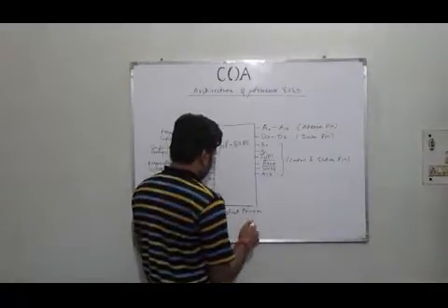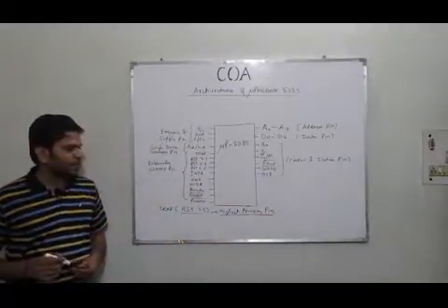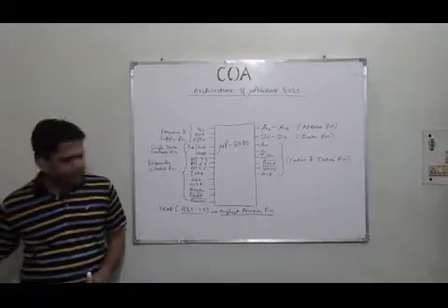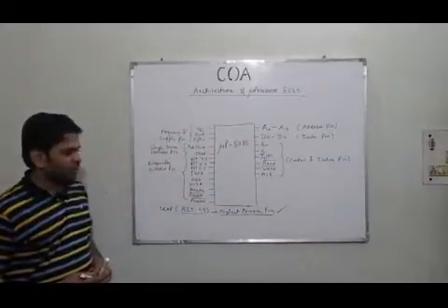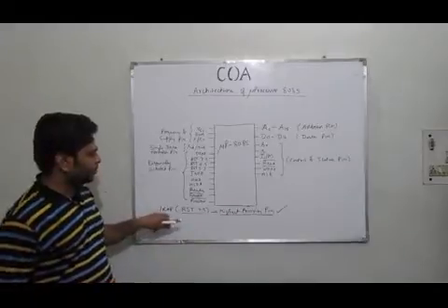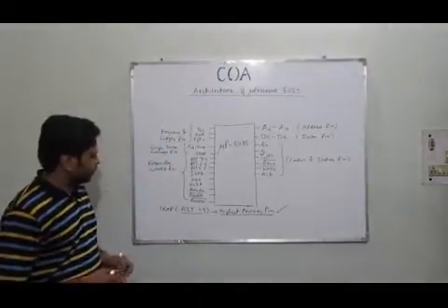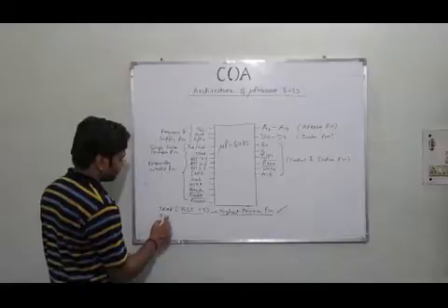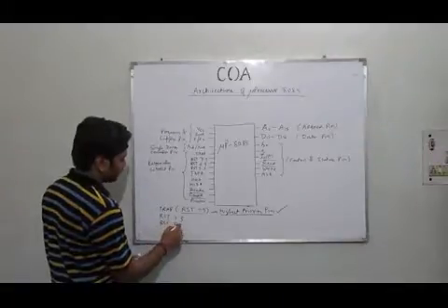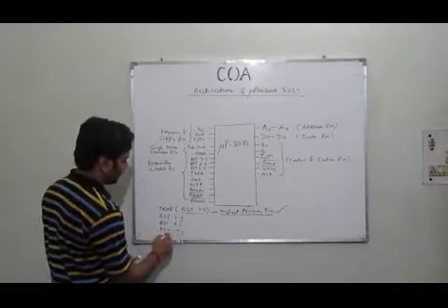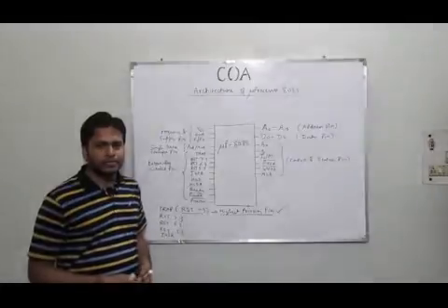So do remember that TRAP is considered the highest priority pin in microprocessor 8085, and this has been asked in most examinations, vivas and interviews. Moving next, we have other pins available like RST 7.5, RST 6.5, RST 5.5 and INTR. We will talk about them in detail under the section on interrupts.